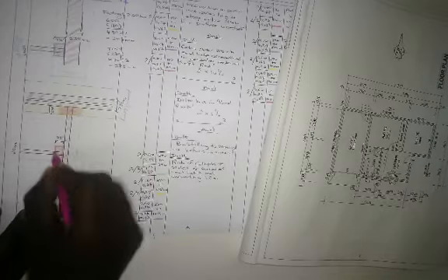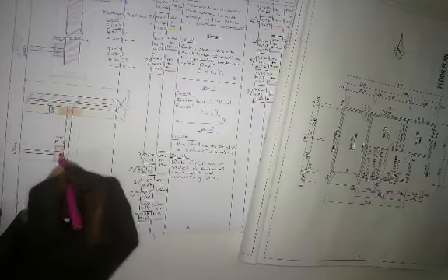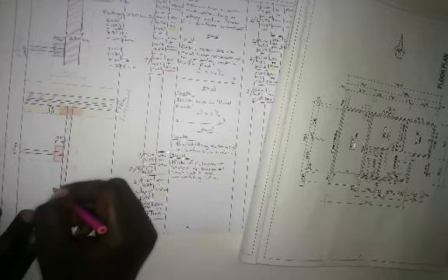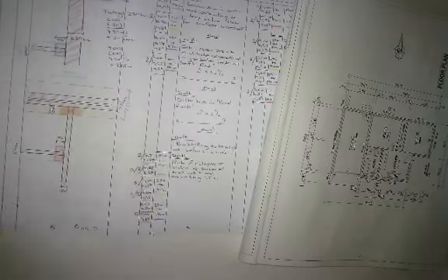You can't re-excavate that part. Here is where a 110 also meets a 270 at a T. So you can excavate there. Here is where a 230 meets a 110. You can't excavate there. Here's a 110 that meets a 110. So this schematic represents the part where it butts against another wall that has been excavated already, okay. I hope this is understandable.